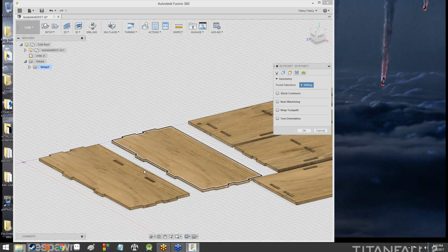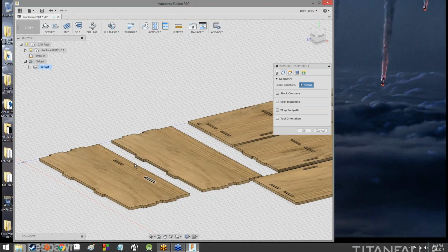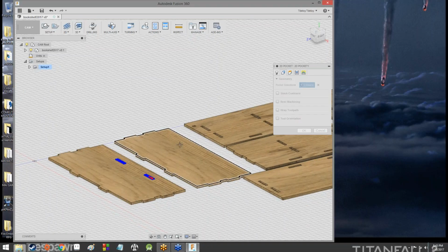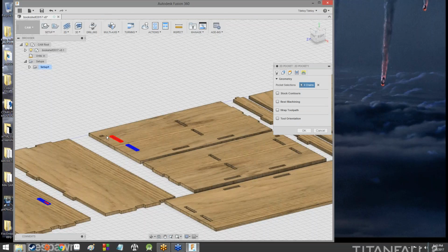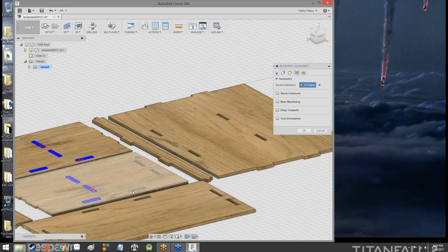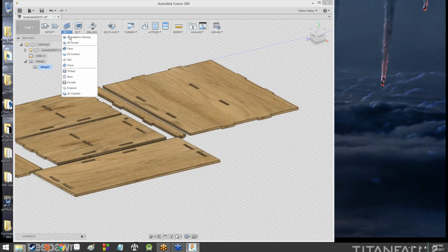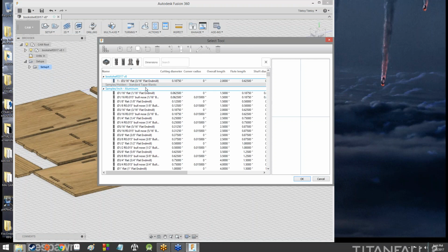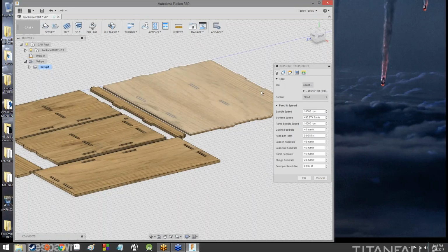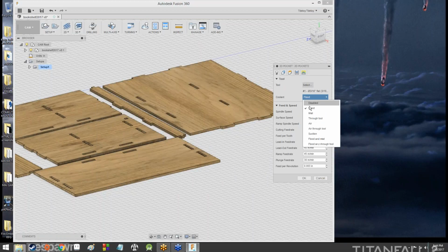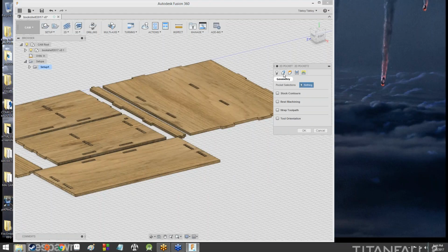Since it's a two-dimensional pocket cut, we can just select a whole bunch of stuff, like all these slots for tabs that are going to be cut by the tool. Now notice I am not selecting these slots down here. I'm just going to move past them. Whoops. Oh no, I accidentally selected a side instead of a pocket, so you want to be careful about that. Don't be a dingus like me.